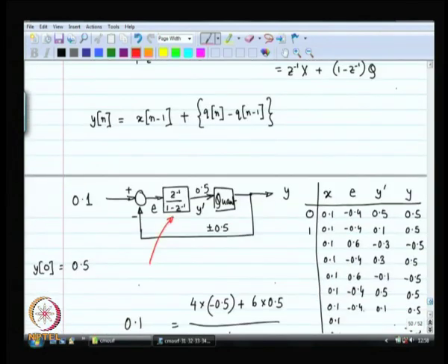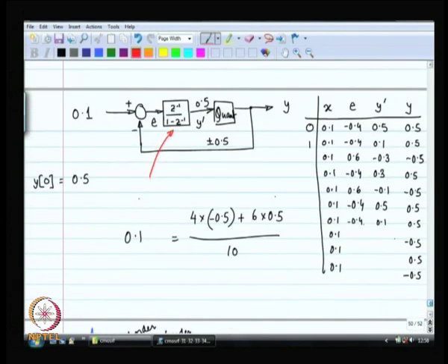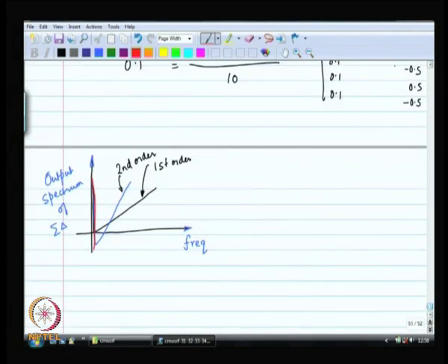So, the sigma delta modulator to use is not something very fancy. An ordinary second order sigma delta modulator will do the job for you. All you have to make sure is that you have broken the periodicity, which second order, or third order even better, will definitely do.